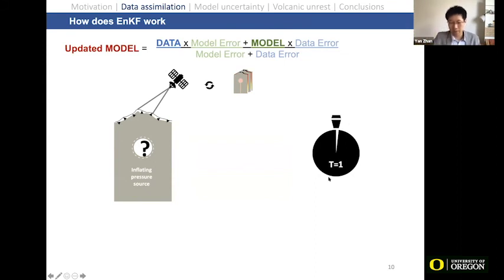The computational time depends on how complicated the model is. Since we are using a Monte Carlo data assimilation, we need around 100 models at the same time. If there are 100 Mogi models, we can do that simultaneously without any waiting. However, a very complicated 3D finite element model, with realistic complexity, will take some time.